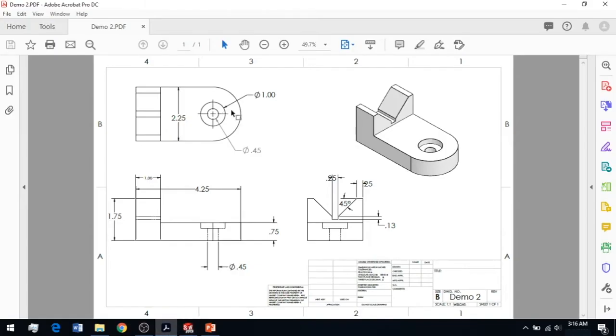So if you go back to your sketch, you can see I need to define the location of this center, which is the center of all of my arcs: the big arc and two other circles. It is half of this thickness. The diameter of this cut at the edge is equal to the thickness of my extrude, which is 225, and from this center point to the edge is the radius that I need. So this point is at half of the 225.